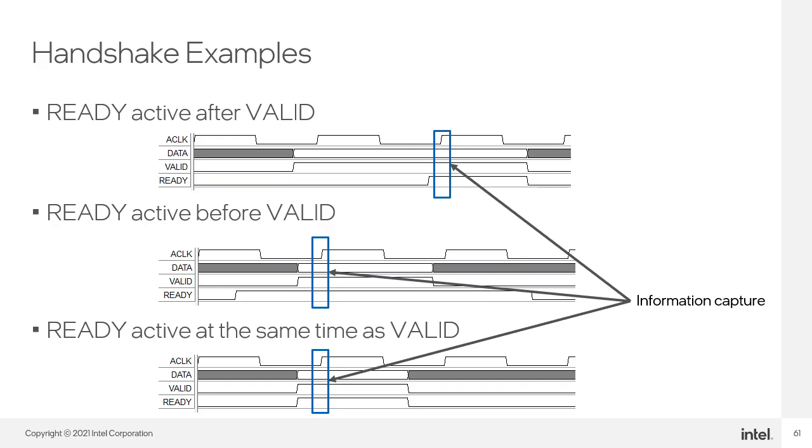These waveforms illustrate how the handshaking mechanism works. The ready and valid signals are available on each of the 5 channels and can be asserted in either order or at the same time to initiate a data transfer. The source asserts valid with the data it's sending, and the destination asserts ready when it is ready to receive the data. The order of these events does not matter.